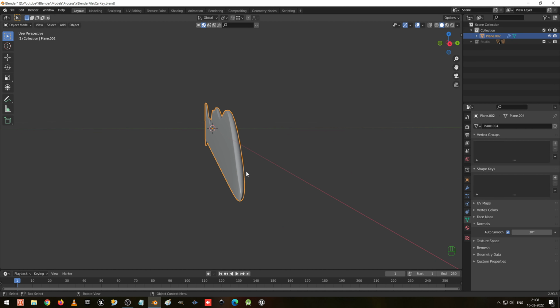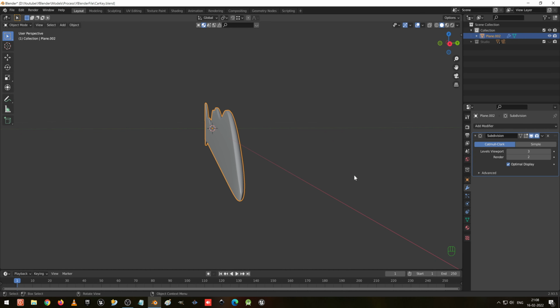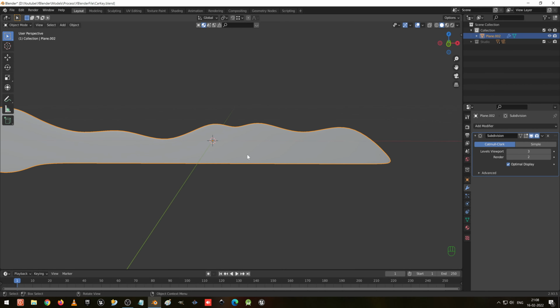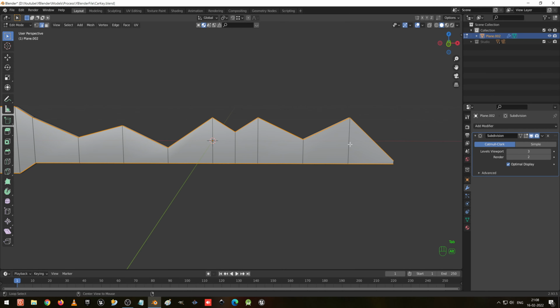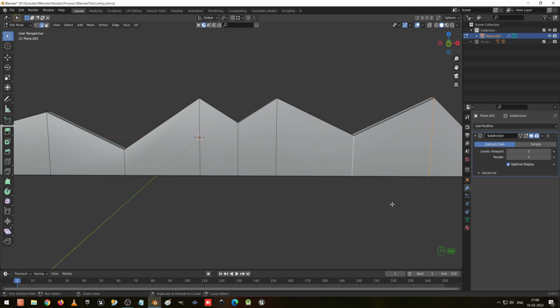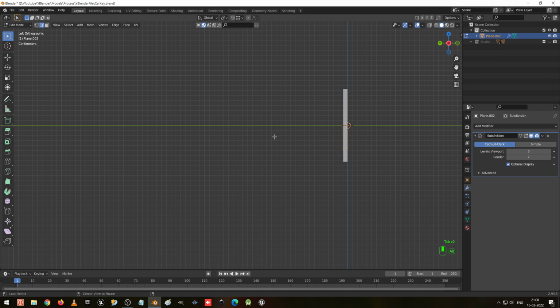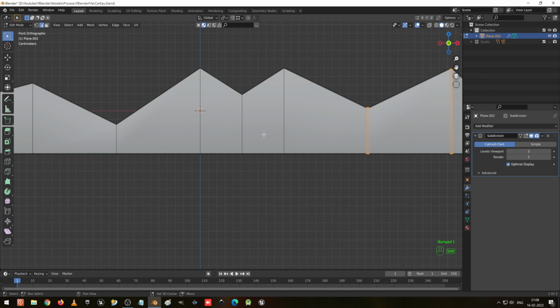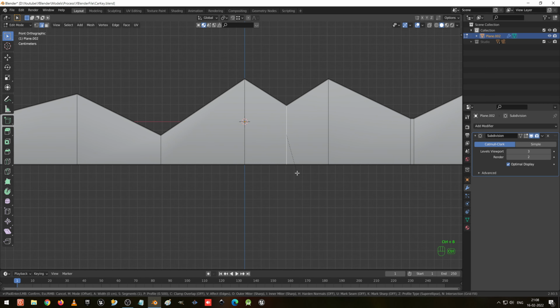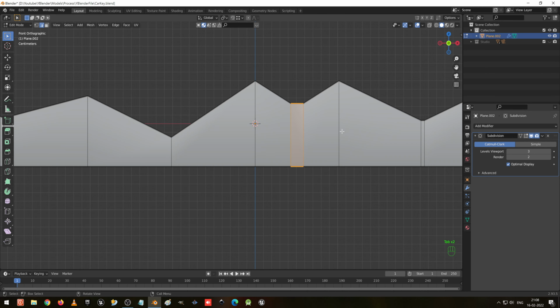Now, we have to shape these corners. Go to edit mode, use your alt key and select this one and these two, press Ctrl B to bevel and reduce the sharpness. I'm going to give the thickness like this, cut for this, and this one I'm going to give a little bit bigger, so let that shape be.